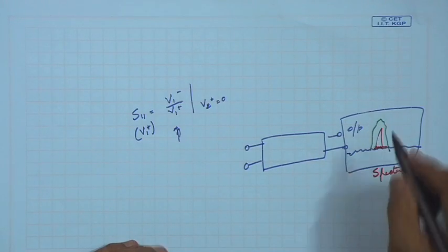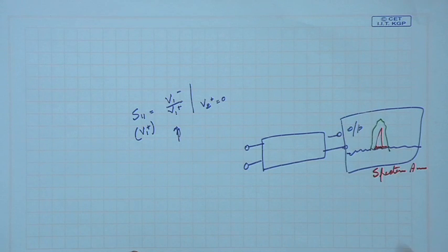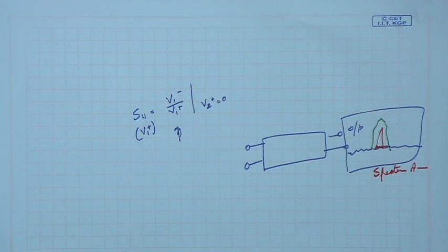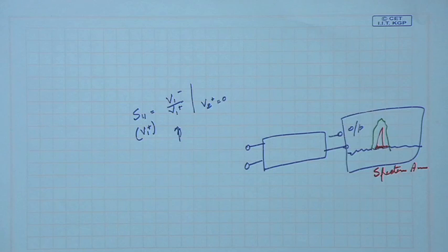It depends on what you prefer. You may call this a signal, I may say no, unless and until it becomes like this green one I will not say so. The green one means his definition of signal requires a higher dB level than the red one's, but whatever you decide is a signal, it means there is something above the noise floor. So the lower range of the dynamic range is fixed by the noise floor.